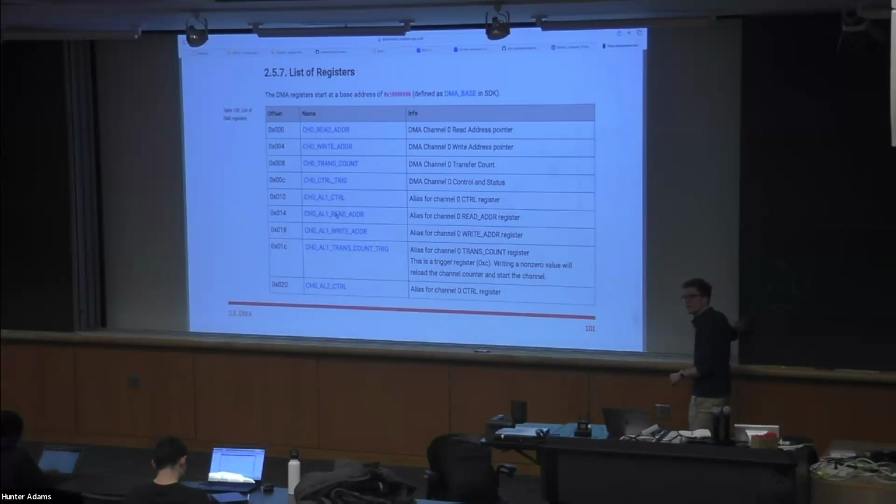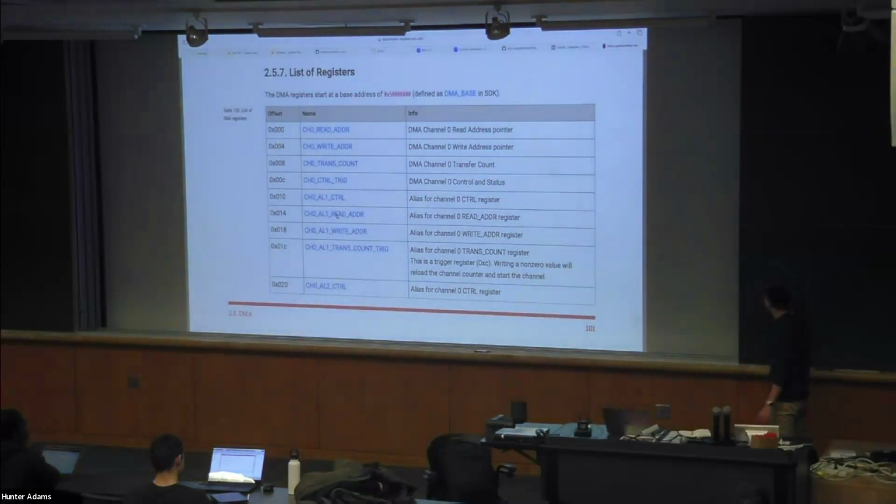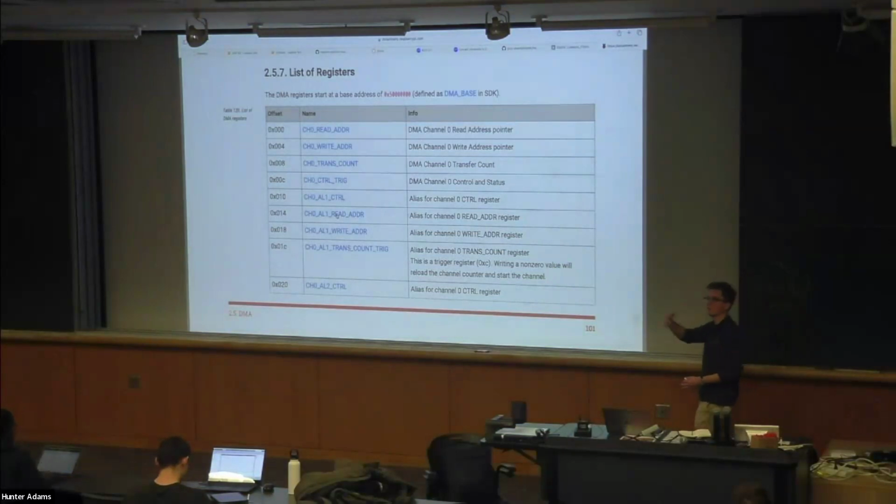But yes, on this microcontroller and on essentially any microcontroller, the power of these DMA channels is that you can point them to any memory address that you want to, and all these peripherals that we're talking about, the SPI channels, the I2C channels, the PWM channels, everything on here is memory mapped. The configuration registers for all of them have addresses that we can go look up. And so, yes, you could use these DMA channels to communicate from memory to any of those other peripherals. You could use them to communicate from one peripheral to another peripheral. You could use them to communicate from a peripheral to memory, from the ADC to memory, for instance.